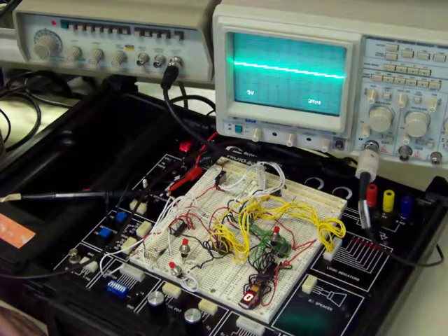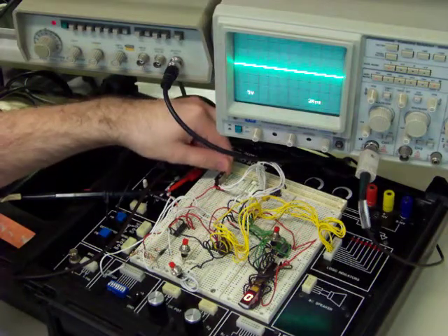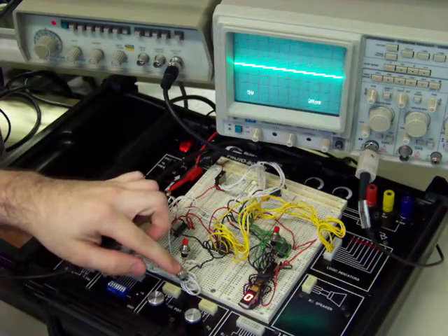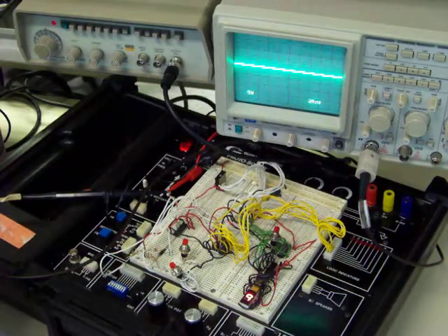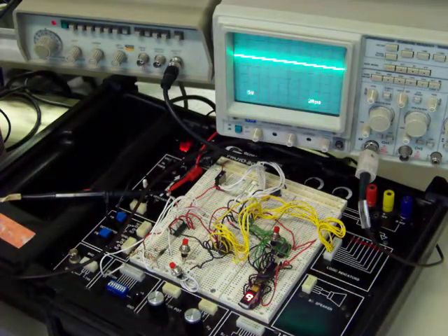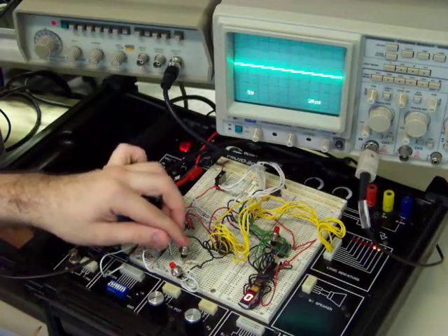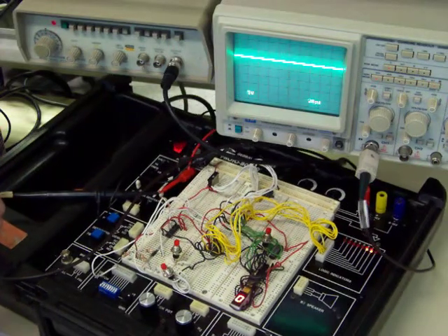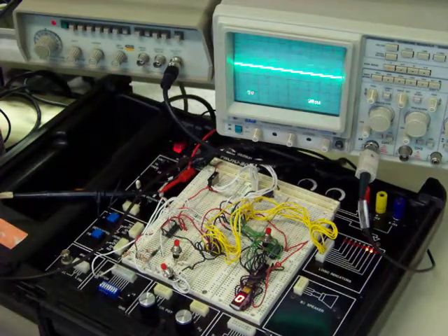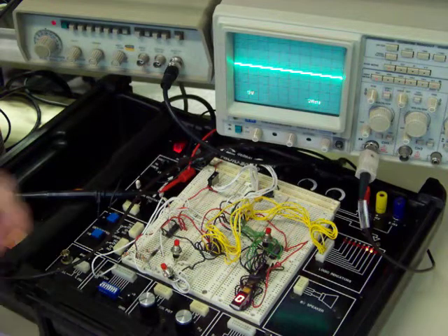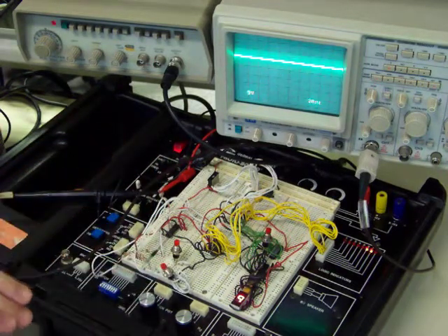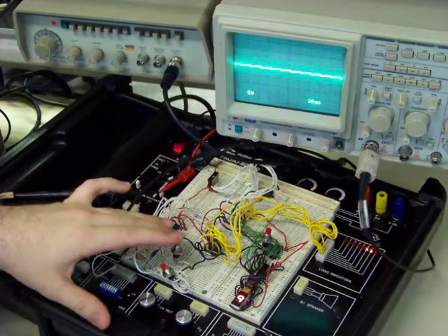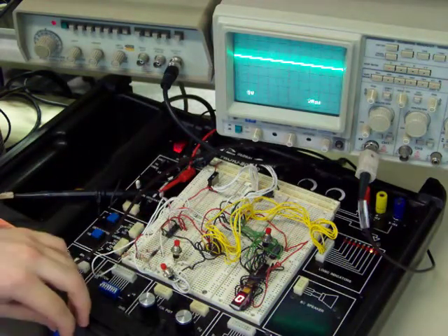So we're at 0. So I have 9. So we'll select 9 on the thumb wheel. We'll load it into the chip, and it displays 9, showing it's holding 9, and we can select another address to enter in at that location, which in this case is 3, which we also need a 9, so we do not need to change the thumb wheel, so we just enter the same 9 in, and we can select another address.